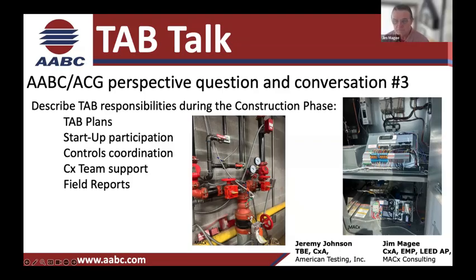Right, yeah. A hydronic system not being flushed properly can be an absolute disaster for a TAB contractor, because he's going equipment by equipment, punching out, finding strainers clogged, finding ports clogged, screwing up his HDM, right? I've had it happen. I've totally wrecked meters before because of the condition of the water in the system.